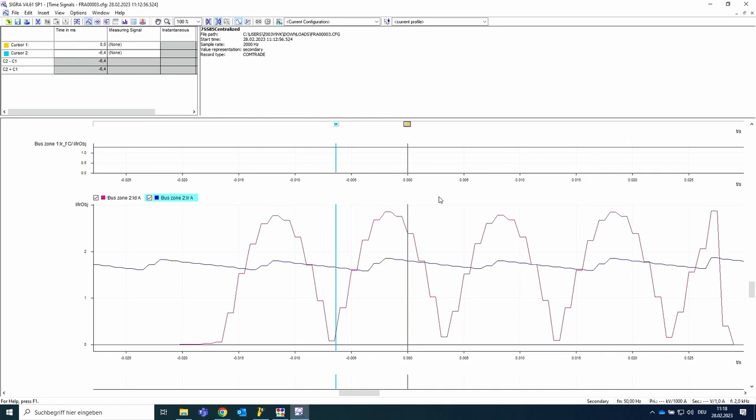So you can see at the very beginning, when the measurement window will be opened again, we will have no threshold exceedings. So it starts here. Nina, you can sign when, okay, here beginning from this moment, we will have a threshold exceeding again, and then we need 4. I think that could be quite fine. So that really at the tripping times, there should be 4 threshold exceedings possible.